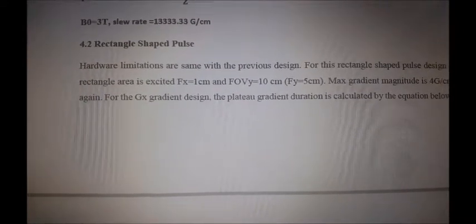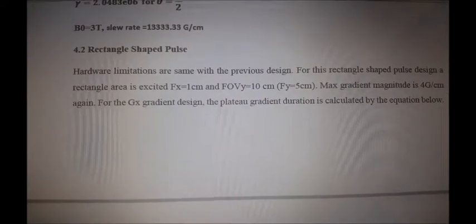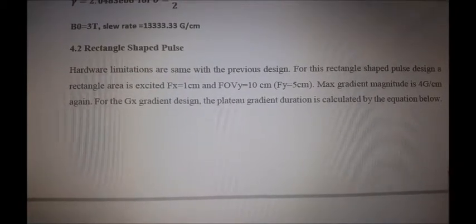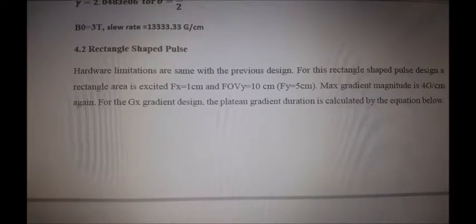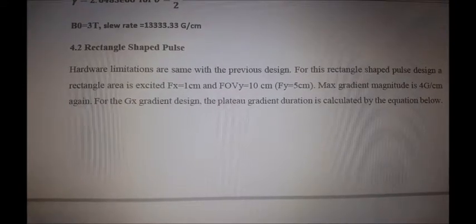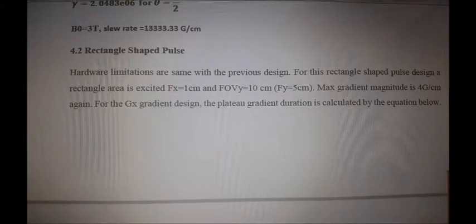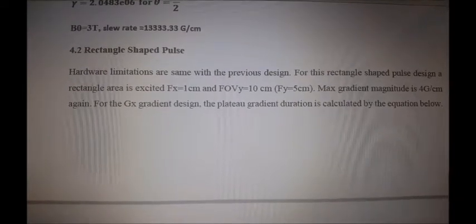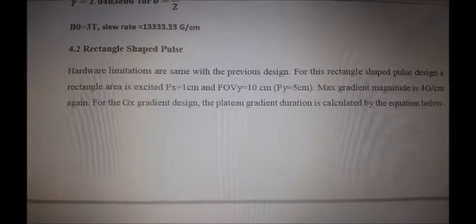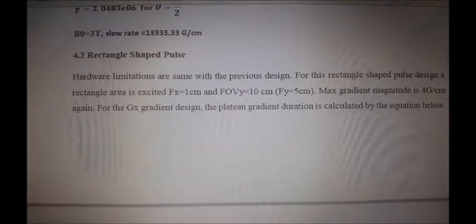As the fourth phase of the project, rectangle shaped pulse design is made. The hardware limitations are the same as the previous design. For this rectangle shaped pulse design, a rectangle of FOV x equal to 1 centimeter and field of view y equal to 10 centimeters is excited. Maximum gradient is again 4, and the